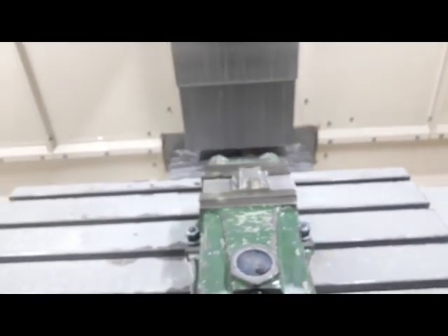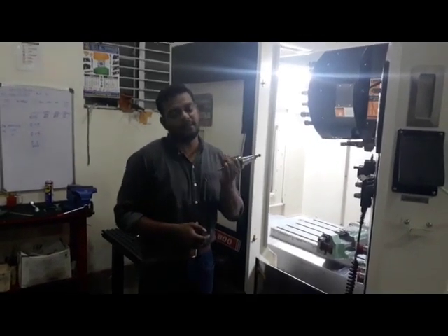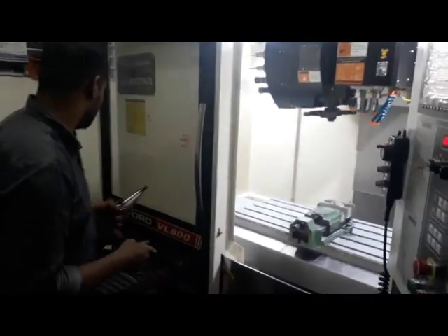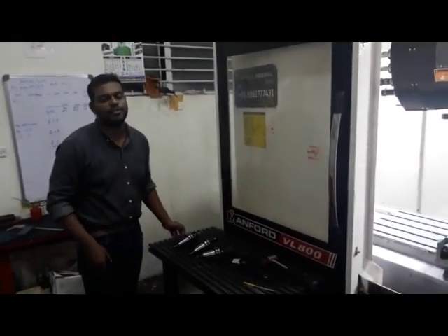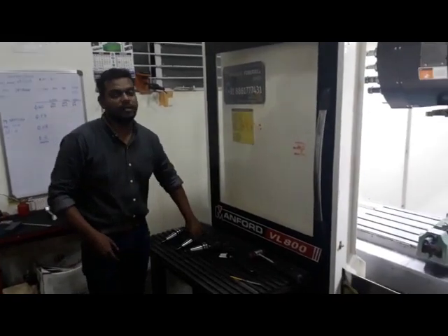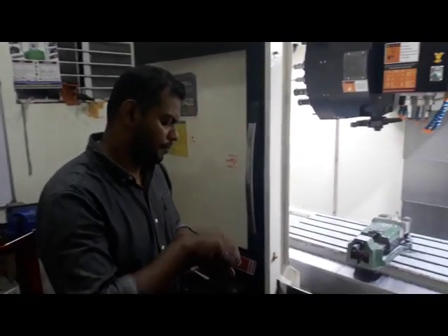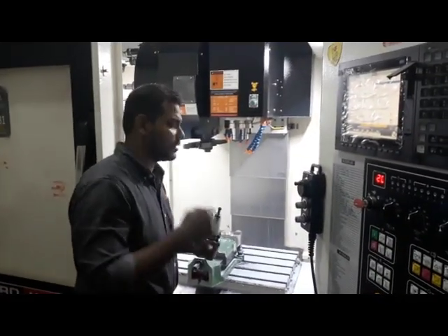Yep, so now we're going to go ahead and machine operation 3 and operation 4 using the 4 end mill, taking out the 10 end mill from the machine. My first and second operation is done. Now I'm going to go ahead with operation 3 and operation 4, which is done using the 4 flat end mill. I'm going to put this holder onto the machine and take the tool offset once again.